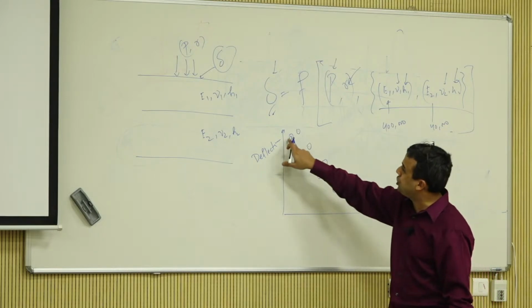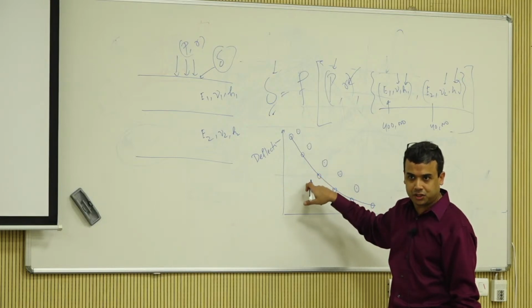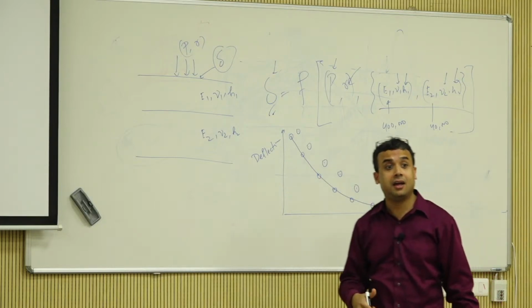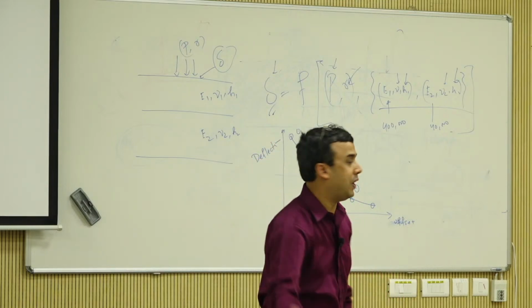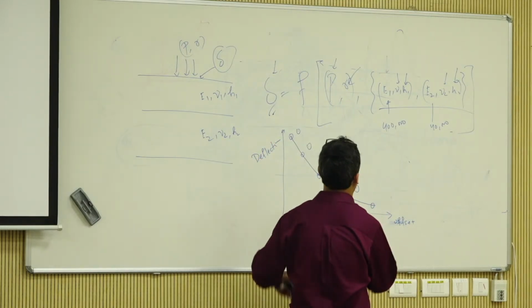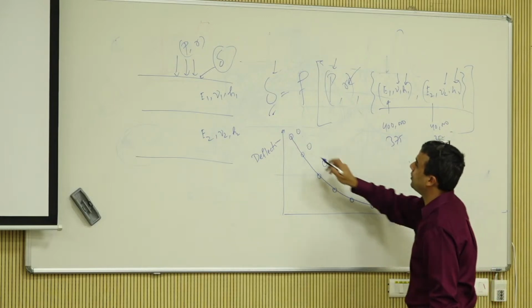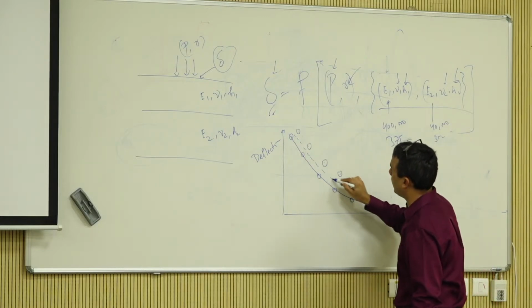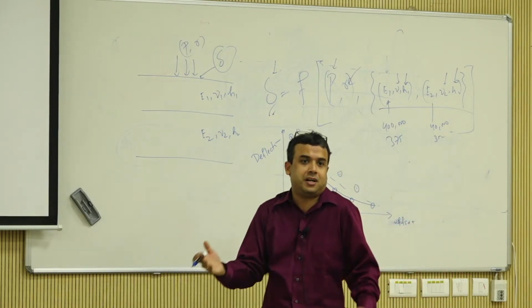So what did I just do? I under predicted deflection, so I overestimated E. So I should be reducing the E somehow. Maybe I should make it 75, maybe make it 35, something, try to make another line. Then you have another one, and ultimately you converge.